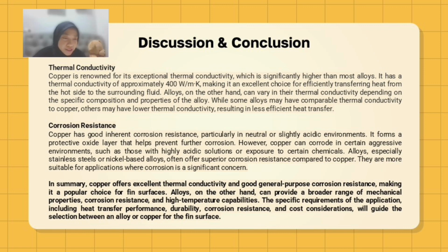Second, the corrosion resistance. Copper has good corrosion resistance, particularly in neutral or slightly acidic environments. It forms a protective oxide layer that helps prevent further corrosion. However, copper can corrode in certain aggressive environments, such as those with highly acidic solutions or exposure to certain chemicals. Alloys, especially stainless steel or nickel-based alloys, often offer superior corrosion resistance compared to copper. They are more suitable for applications where corrosion is a significant concern.